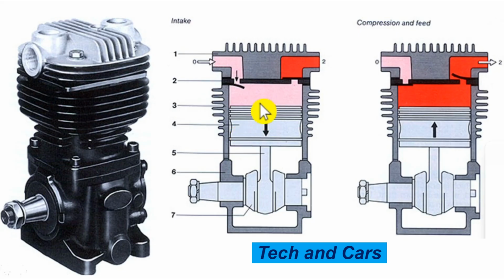Use the correct oil for lubricating the compressor. The compressor is a hard-working engine-driven pump, so it needs oil that can handle the high temperature and that can handle the moisture that comes with the air itself. So the oil has to be a recommended oil by the manufacturer, and it has to be replaced regularly.